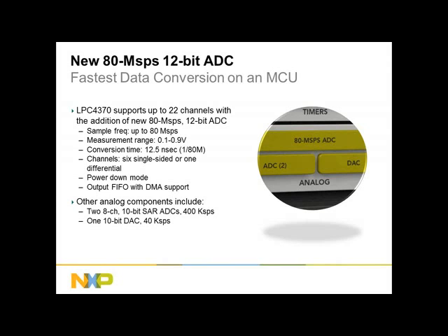So obviously it depends on your use case, whether you need that many or whether you're just interested in the high-speed lines. Now the measurement range going in is a little bit small, so we'll require some conditioning circuitry in front of it. We do have some examples. I'll talk about the lab tool in a little bit that we've done that you can take and modify.